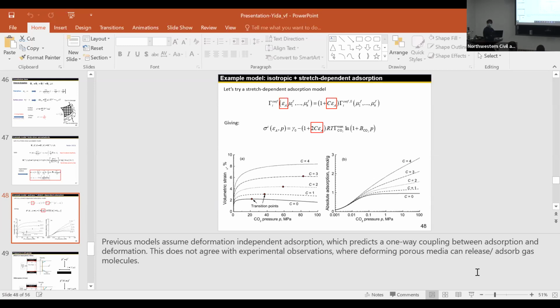In fact, when the surface is stretchable, the surface tension concept should be replaced by the surface stress, as proposed by Shuttleworth's equation. There are a lot of things to explore along that direction, because the Shuttleworth equation tells you surface stress, but that's again a scalar. What if you stretch the surface along this direction or that direction? So it really should be a tensor.